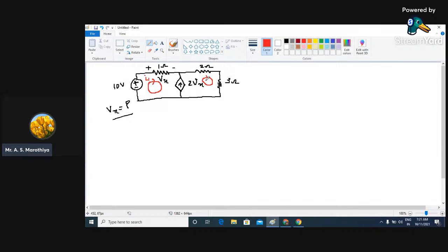In the same way, the value of current flowing through mesh 2 is say I2, again in clockwise direction. Now what we need to write over here: first we are going to apply Kirchhoff's current law to find out the resultant equation of current based on a common current source which is connected between mesh 1 and mesh 2. If you focus on this structure, here we have a voltage controlled current source, the direction of current is upward, and the magnitude is 2Vx.